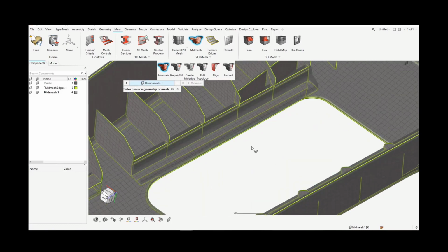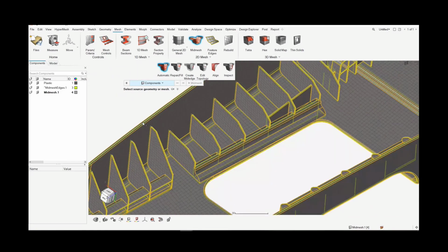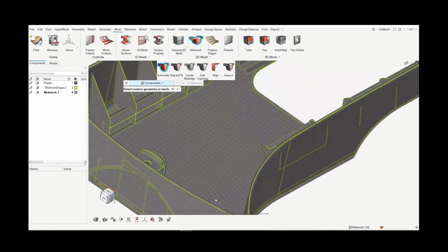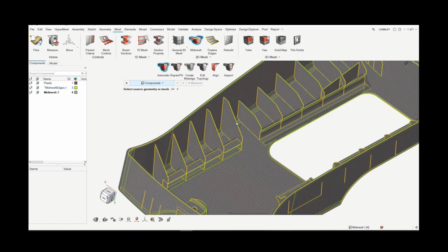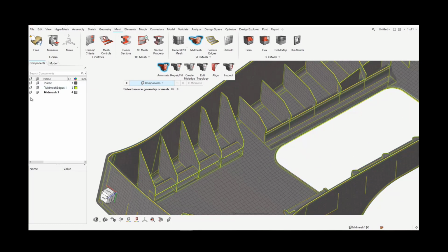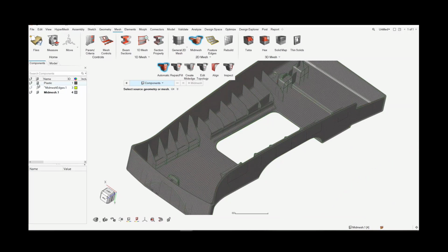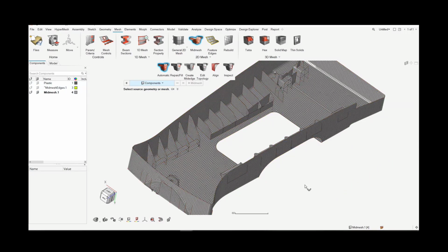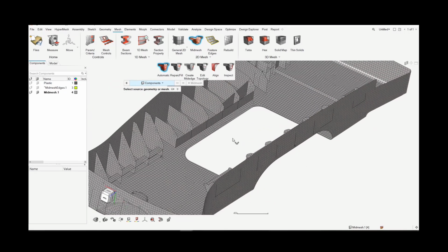All right, so first thing we notice here, the geometry part of this has been switched to more of a transparent view, and we have these mid-mesh edges here. I don't personally love this visualization all that much, so I usually opt to come in here and turn that off. So one of the first things that I would probably do here is make sure that things that look like they are connected are actually connected.